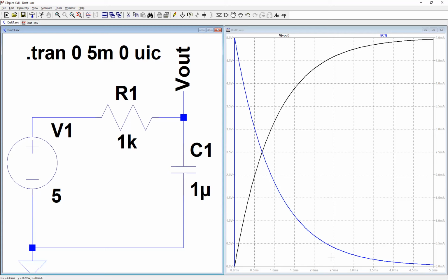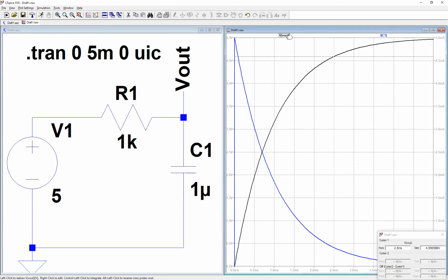And I want to know the voltage. So of course, here I can see this is 2.5 milliseconds, and then I'm going up, so it's approximately here. I can say it's between 4.5 and 5, but there is a more precise way to do this calculation, to have this value here. I can click here with the left click, and one cursor appears.